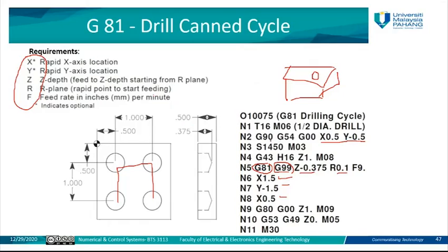Other parameters here, as you can see, in any of these codes, you can refer either for speed, for selecting the tools, for G90 here when you define either absolute or incremental coordinates, okay, or you have to decide about the length compensation of the drill tool, or you will need to decide about the compensation of the drill itself, the size or the diameter of the drill. All these parameters need to be defined.